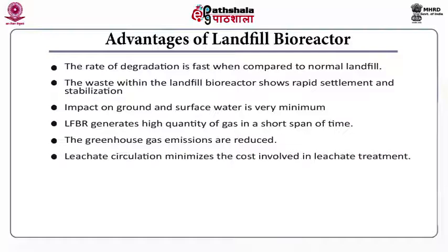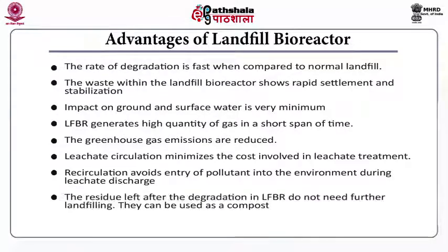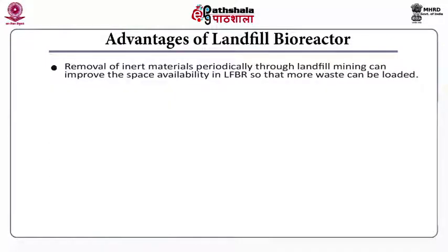The leachate recirculation minimizes the cost involved in leachate treatment, and recirculation also avoids the entry of pollutants into the environment during leachate discharge. For the residue left after degradation, you do not have to provide extra treatment to manage it. It can be used as compost. The inert materials are generally removed periodically through landfill mining, and hence more space will be available. That is again an added advantage.